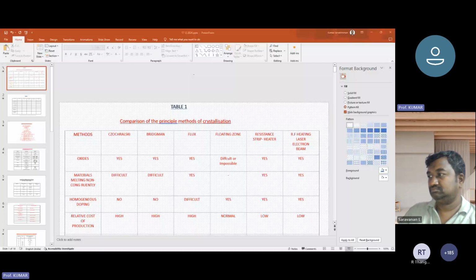And similarly, when the devices are fabricated on a circular disk of material or a wafer, I showed you yesterday some squares which I defined as the areas of the devices. And those squares are kept inside a packaging system, which we call an integrated circuit. Many of you use it in your computers. For that to happen, the materials have to be diced, and dicing can be done along a cleavage plane once the devices are fabricated on a given substrate.